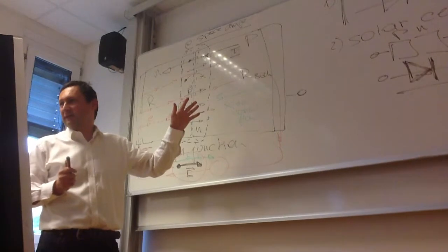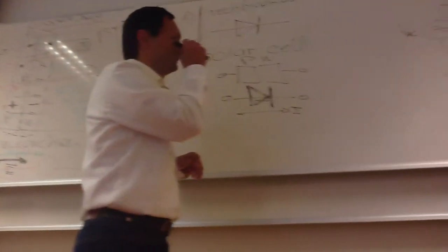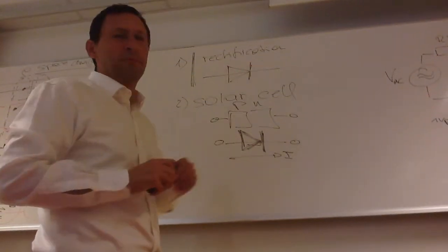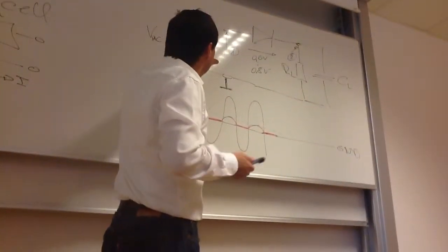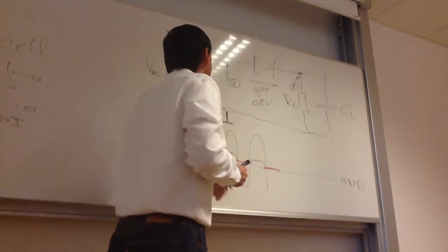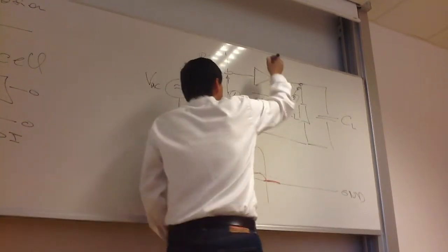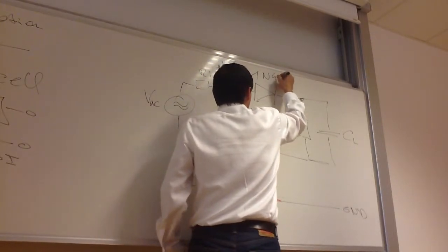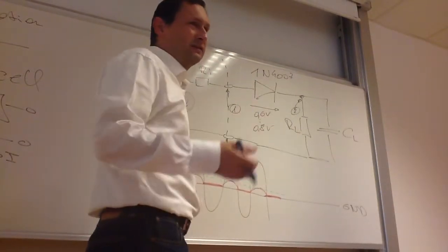So by now you should know the physics behind this PN junction. And that's a simple application circuit. We can put it to life in the lab. This is the generator. It generates our AC voltage. For a diode, you can use a 1N4007 or something like that, doesn't matter, because every silicon diode exhibits the same characteristics.